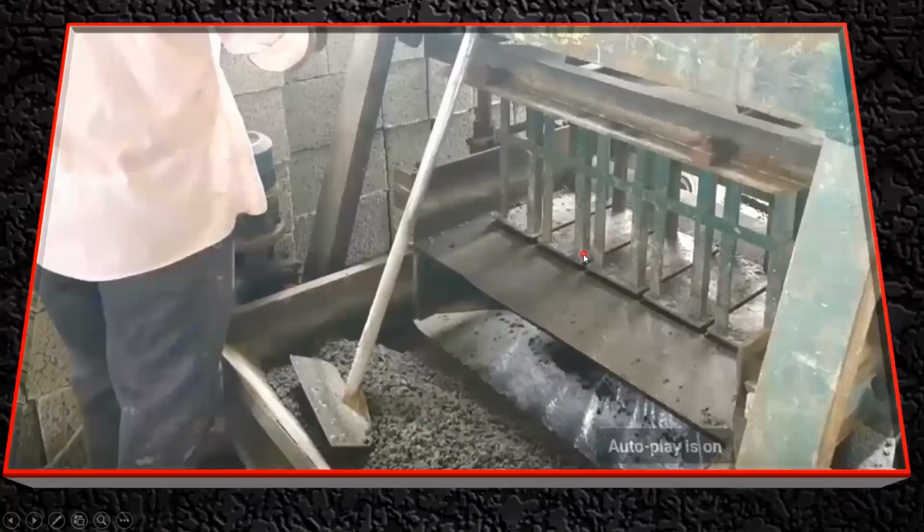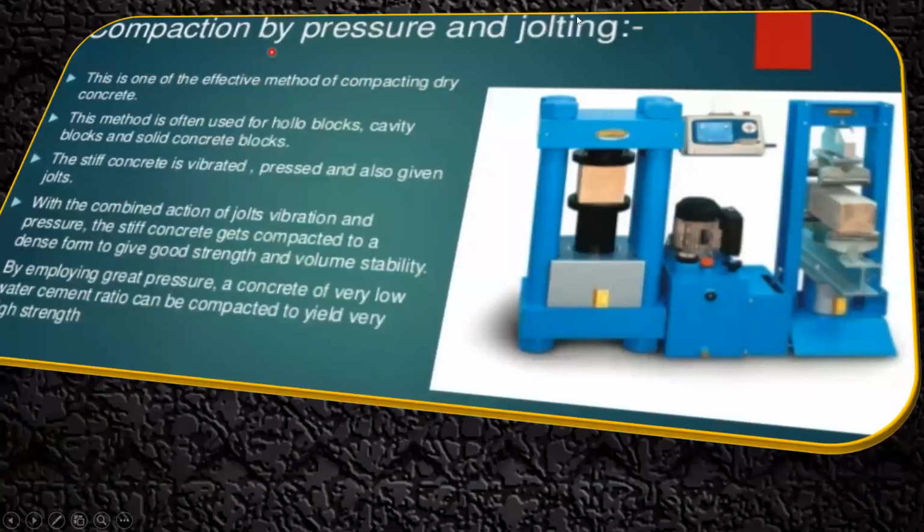The next one we have is compaction by pressure or jolting. These are just a machine to show you. The main points are here. This is one of the effective methods of compacting dry concrete. This method is often used for hollow blocks, cavity blocks, and solid concrete blocks. You might have seen the solid concrete blocks which are available in the market, which have a size of around 600 mm by 200 mm by 150 mm, right?